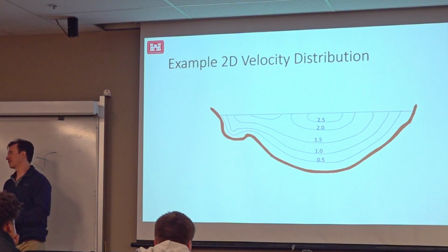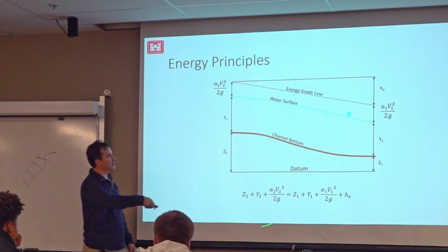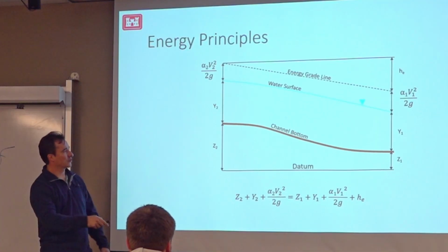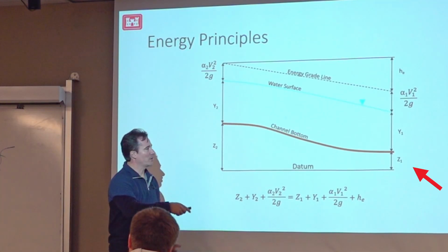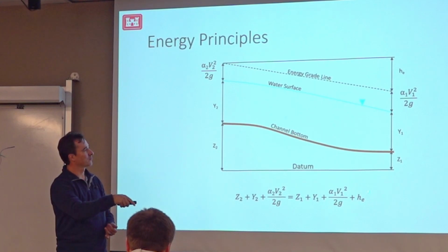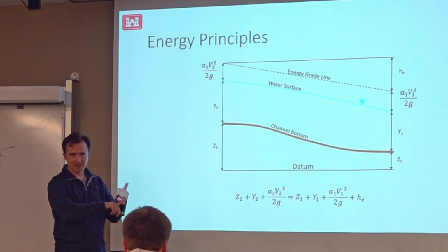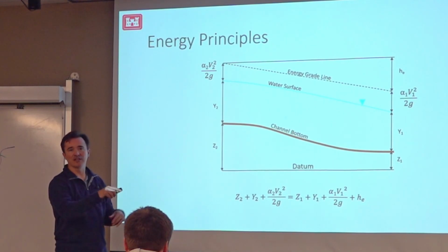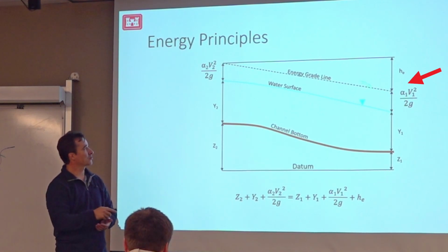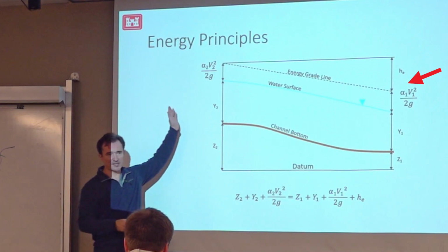So go back to the plot. All right, this is a cross section, this is a cross section. I should have explained it better. Starting from downstream you have a solution which includes your water depth, your water surface elevation, and a flow. You have a kinetic energy head, right? So this is your energy grade line. And you want to know what your water surface is up here.